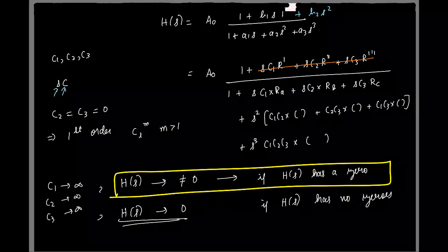For finding if I have one 0, I am taking one capacitor separately and putting it to infinity and checking. If it has two zeros, you can argue the same way. You'll have to take two caps at a time and simultaneously tend them to infinity.